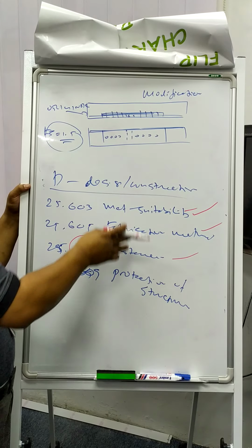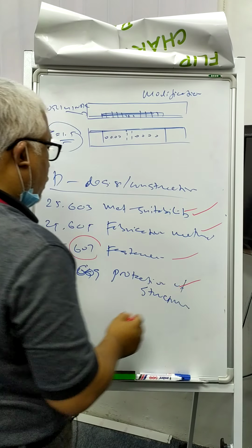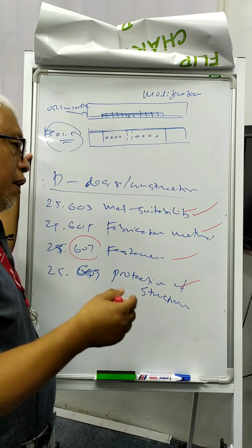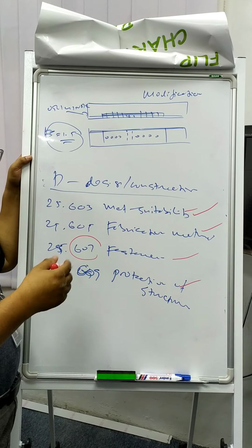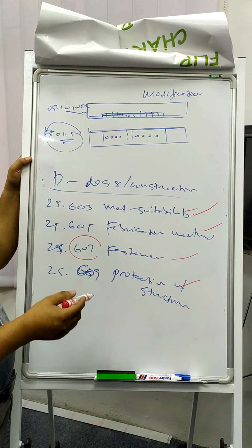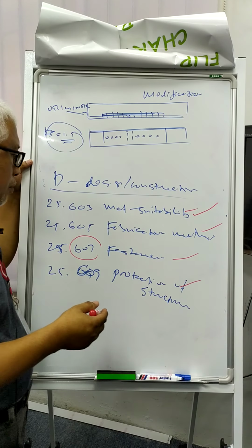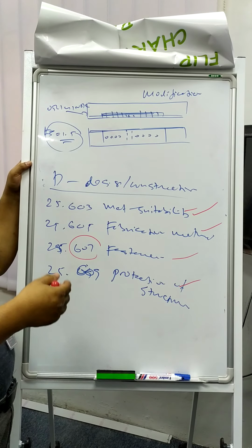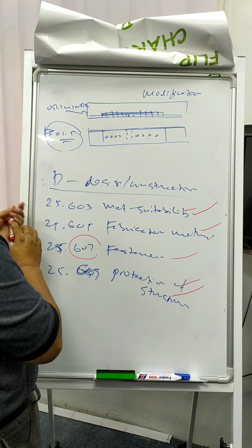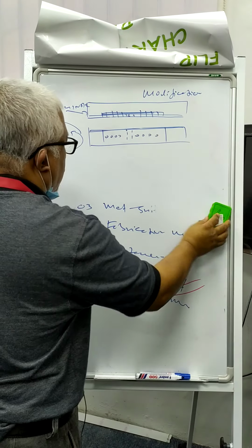The best is you use whatever is available from the SRM, then you have no problem. 609 protection of structure, as we mentioned earlier, since you are using AISI 301, that is stainless steel, there will be a dissimilar metal issue, so we have to cadmium plate the AISI 301, and the cadmium plating process, everything is also from the SRM, so we have no issue. So this is easier, referring to the design and construction of the repair according to the structure repair manual.